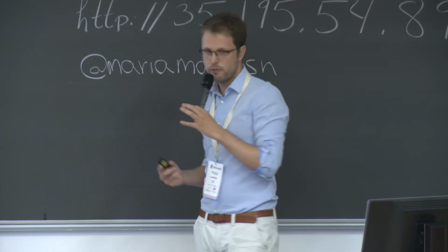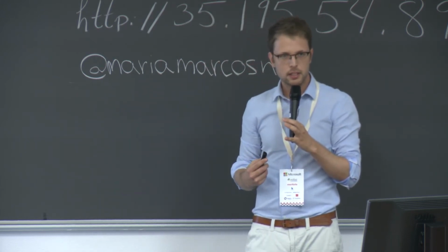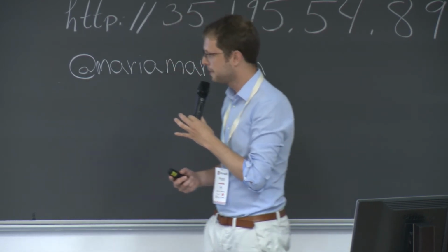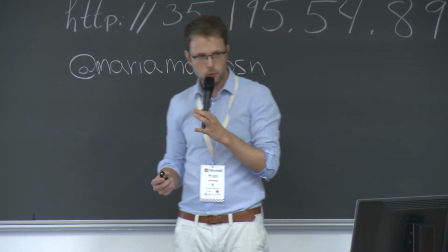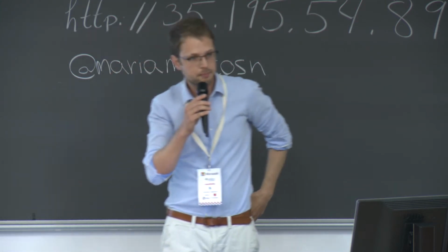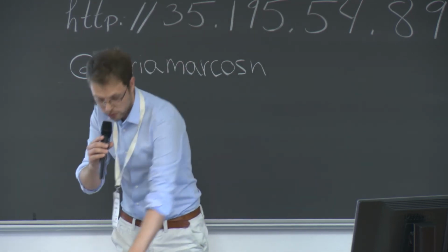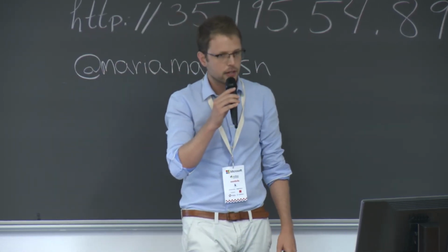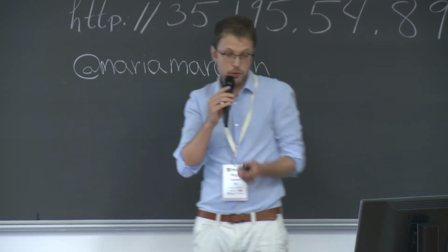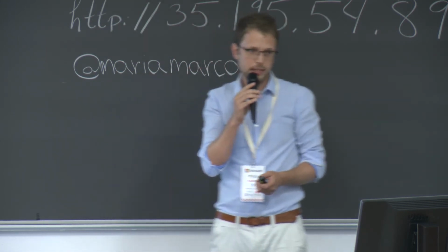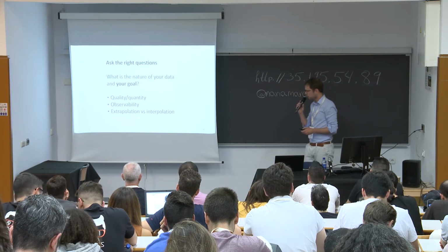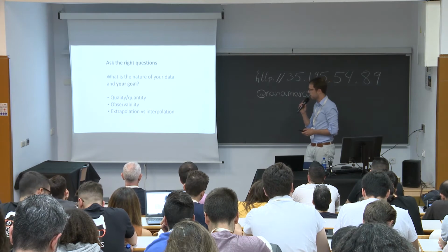So what is the nature of our data? Our data is important for us, the dynamics, depending on your goal. You need to think about the quality and quantity. In chemical processes, sensors are usually bad. Or not bad, but there are many things happening. There are many operations, many shutdowns, many different things within 2 years that, if you don't know, might seem like bad quality data. But you have to always think about the nature of that data, because it might carry more information than you think.